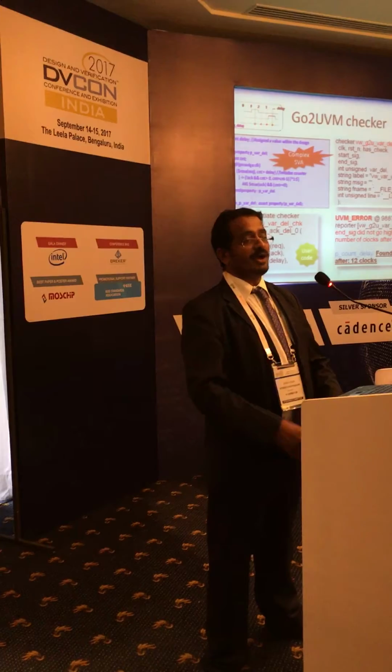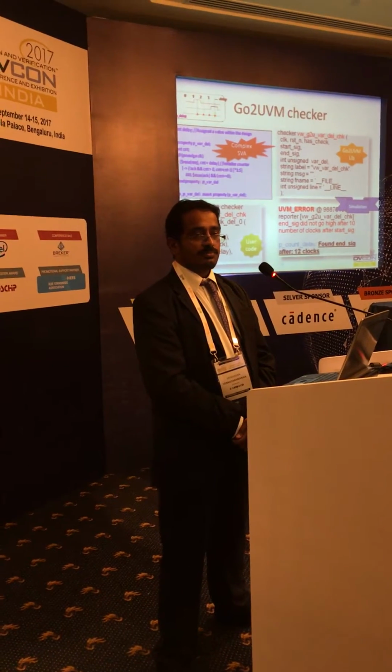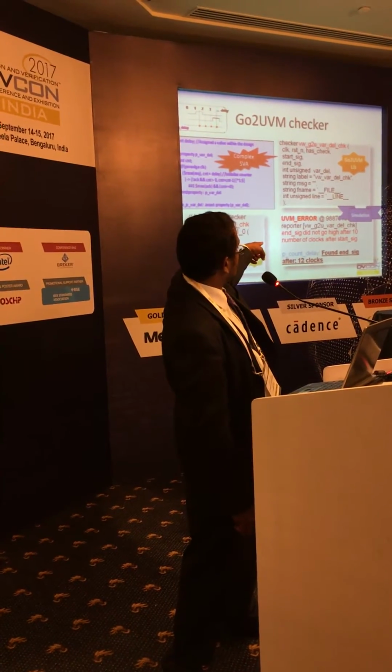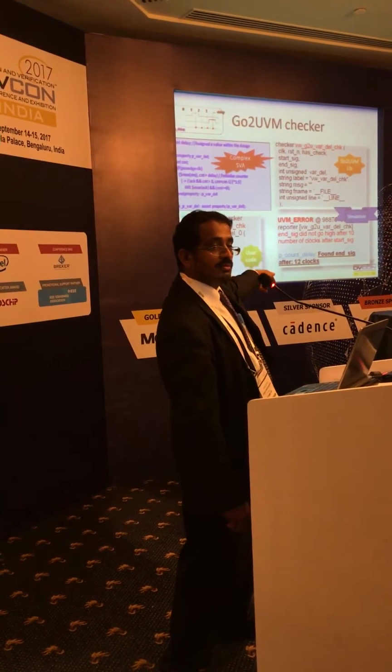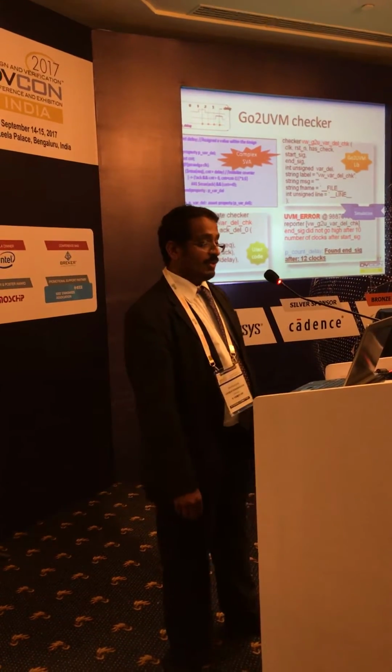But can you also do a debug for me? Meaning without me having to dump it and rerun it. Here is a debug. So let's say if we didn't get ack in 12, then your assertion has already failed at 10. Right, but your checker is still active. That's right, the checker is active. Does that have a performance issue? Yeah, why not? I mean, it could.